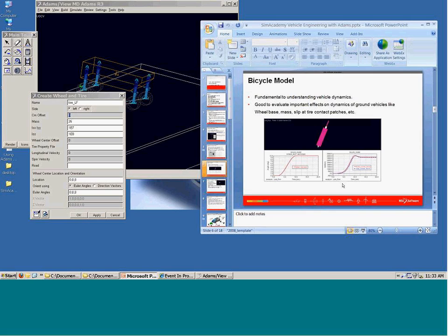But tires are one of the most complicated force objects in a multi-body dynamics model. So you can have a variety of different formulations that give you good enough numbers. The choice of tire depends on the kind of event that you are simulating, but in addition it is also dependent on the data that you have.